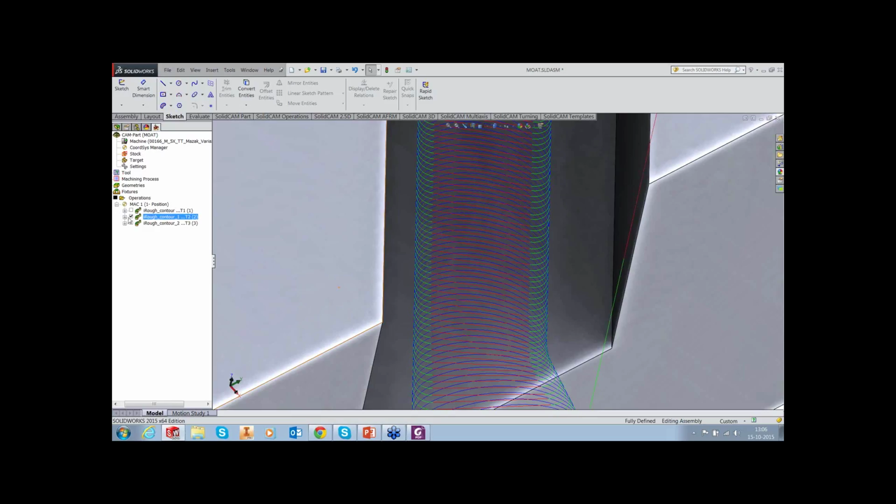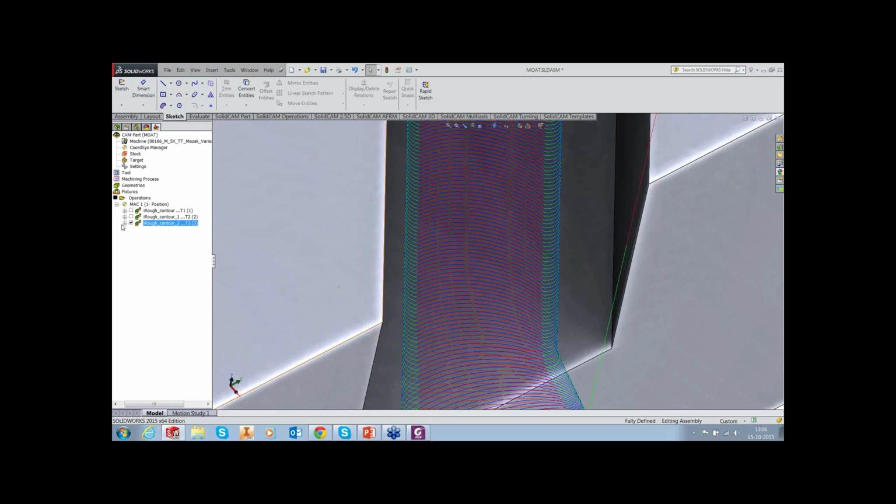And the width increases with a 10 diameter tool. So you have to make a decision. If the particular slot allows you to go with a slightly smaller diameter, it would always be advisable to use a smaller diameter than to use a big diameter and try to just cut very fast on a very small area of movement.